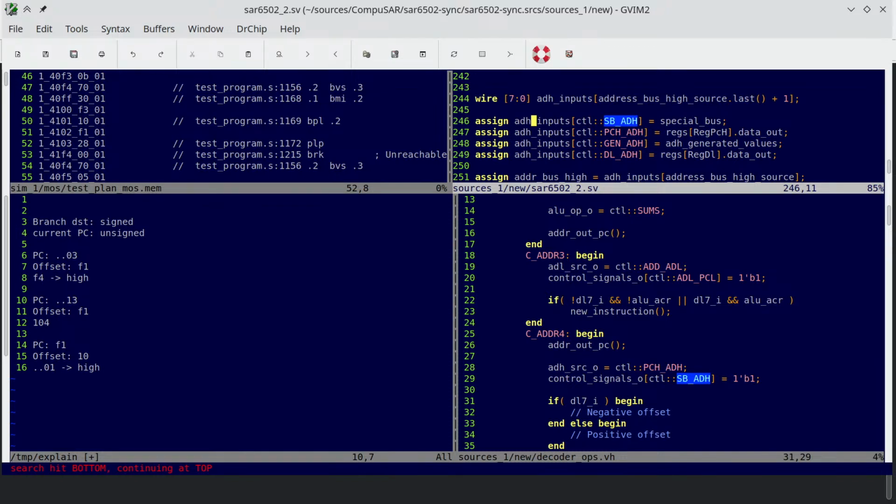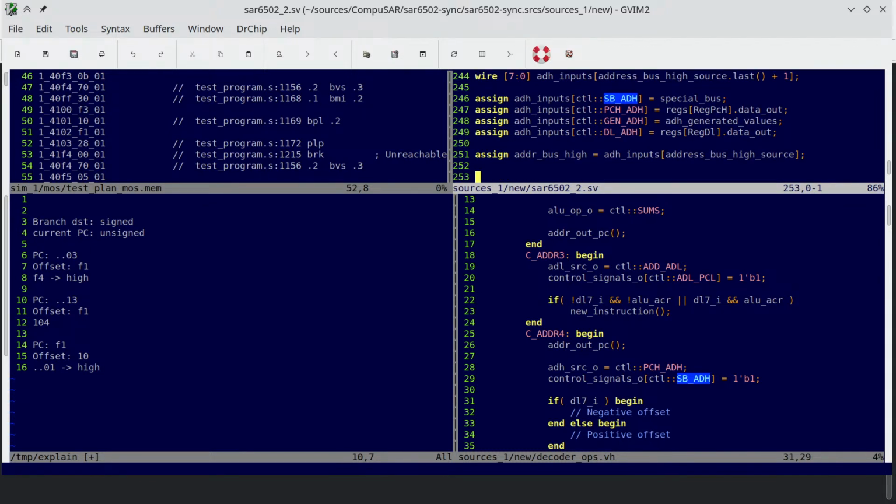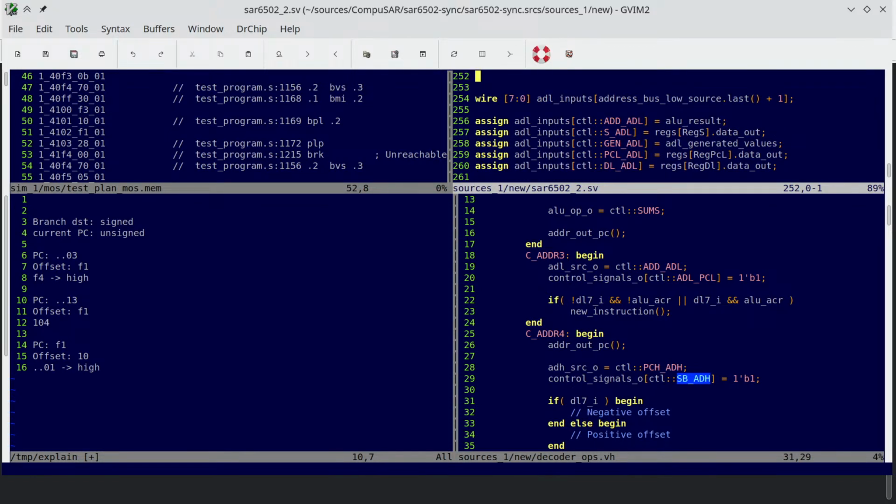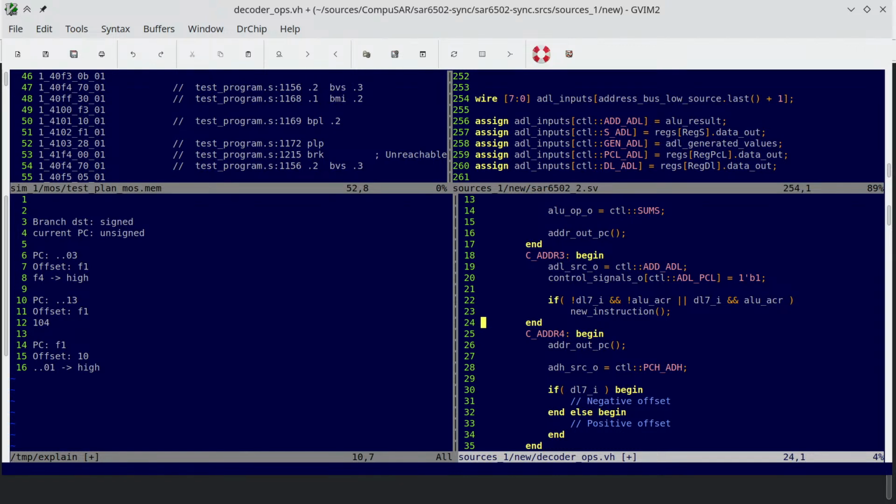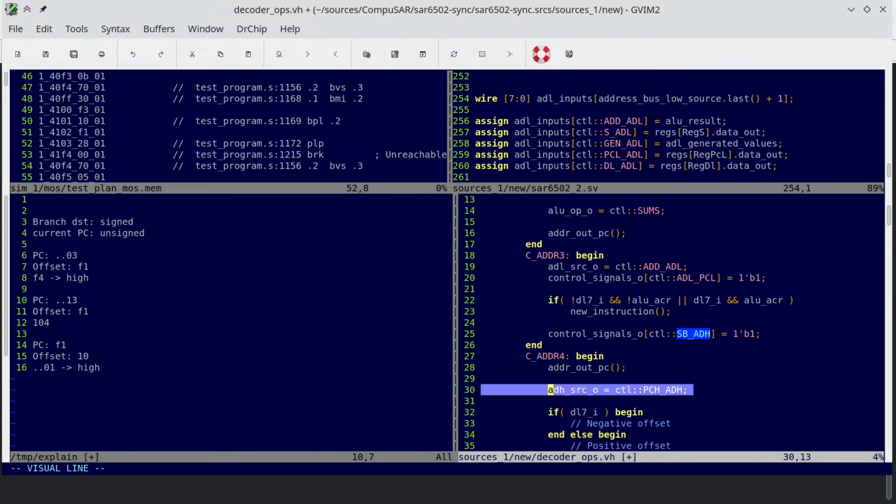Thing is, the opposite direction is a bit problematic because if we have both directions, we have a loop with no clock in the middle, and FPGAs really don't like that. So the opposite direction is going to happen with a register that uses the clock. That introduced latency, but we're fine with the latency. In fact, we can do that in the cycle before, and then we won't even need the latency.